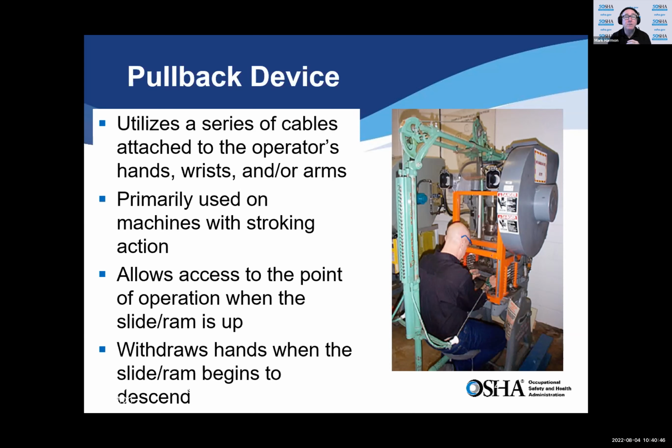Around the machines, I would say, think of the glove as if it has the opportunity where it's going to grab you or pull you in, right? Because the glove would be just like your sleeve, or what we were talking about with long hair. If it has that chance to grab you and then pull you in, that's a hazard. So you should be thinking of that.